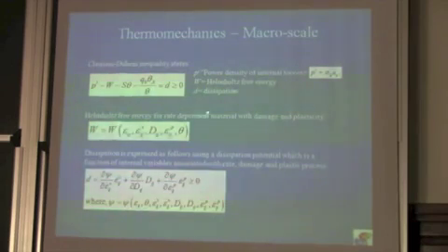And for the type of materials we are discussing, which are rate dependent and have damage and plasticity, we will introduce a Helmholtz free energy which would be a function of all these kinematic variables, where the one with the superscript V refers to the rate part or viscous part, D is damage, and then the plastic internal variables. Right. So in this work, later we will drop the heat-related terms, so this theta, the temperature, will become irrelevant, at least for discussion today. Okay, so that's the expression for free energy.